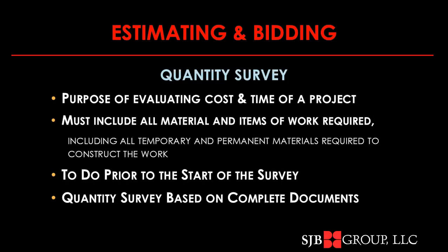And we need to be using complete documents, including all the addenda. The purpose of doing the quantity survey is because we're evaluating the cost and time it will take to do a project. We must include all the materials and items of work required, including all temporary and permanent materials required to construct the work.